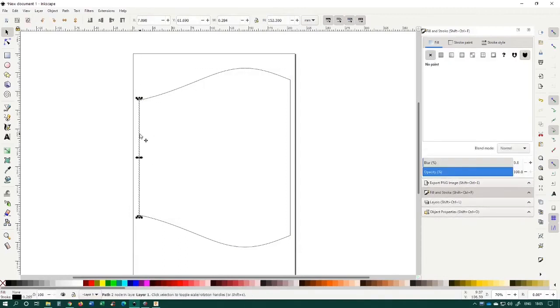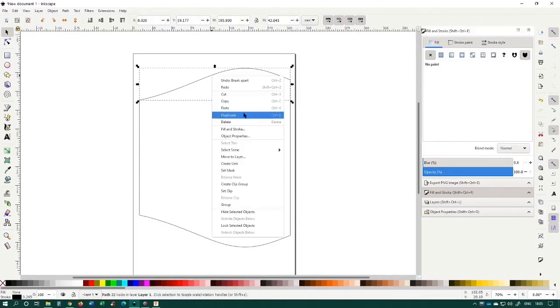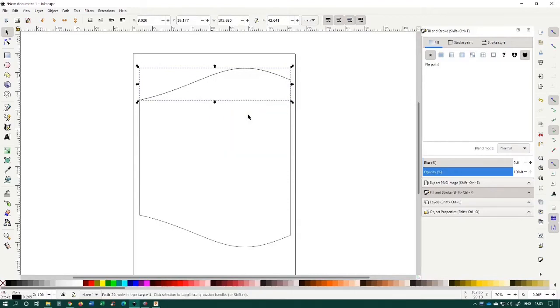After this, you can select each line and duplicate it by right-clicking and selecting Duplicate, or by pressing Ctrl D. Then it's just a case of moving the duplicated line offset from the original one a sufficient distance to allow for joining. You can use the arrow keys to move the line perpendicularly and with fine control. Do the same for each line and then join the newly spaced lines with short connecting lines, which will snap to the line ends.